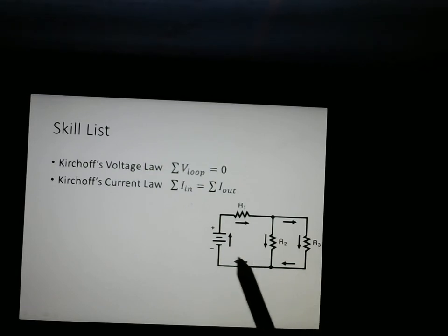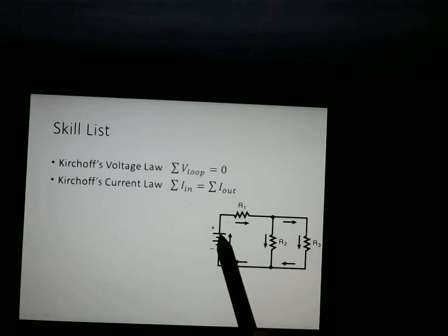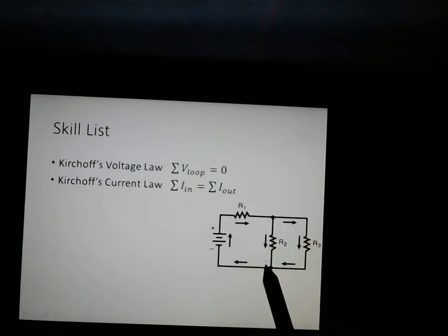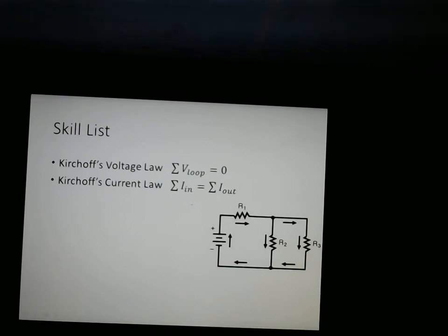So here on our diagram, we can see our battery, because there's two cells, and here's a loop from here through R1, R2 back to the terminal. But there's another loop as well, R1 through to R3, and then back to the terminal. And so remember, that implies that if the voltage through here and the voltage through here has to add up to 0, these two must be equal to each other because they're parallel.